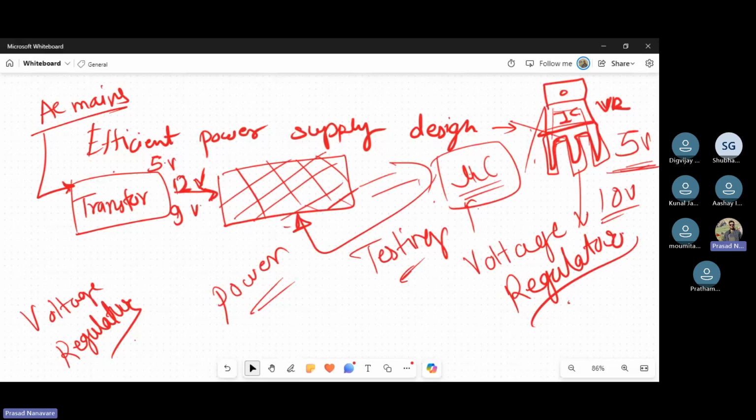Okay, so low power voltage regulators use low dropout voltages. Okay, or buck converters that efficiently step down the higher input voltage to the required supply voltage for the system. Okay, this is also talking about the voltage regulators. Okay, the efficiency of voltage regulators significantly impacts the overall power consumption.